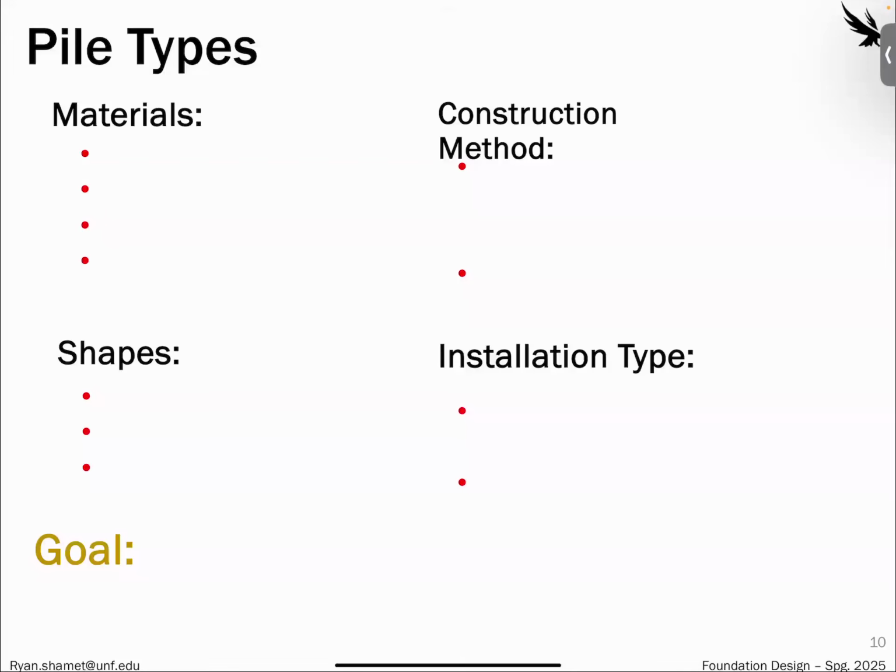So if you know you're going to achieve significant depths, then the steel pipe piles might be the way to go. And some of those, again, you can see the number. I think this says 354 on some ends. There were really, really deep pipe piles, especially over Lake Ivanhoe, just north of downtown, because that lake is deep with organics and was formed by a bunch of old sinkholes and all that stuff.